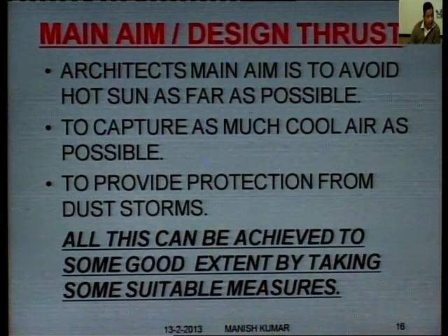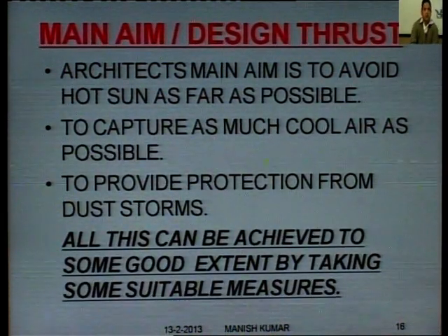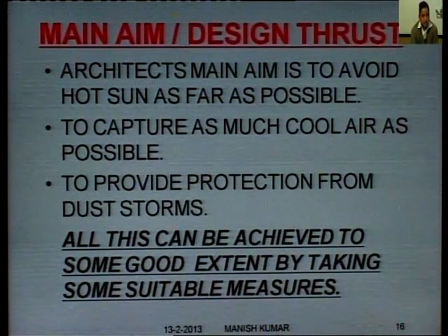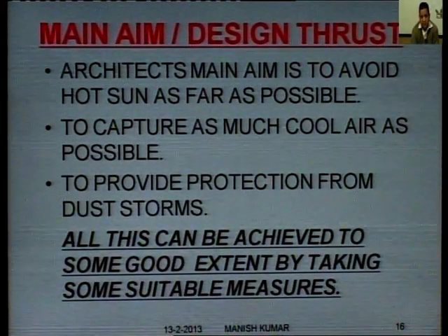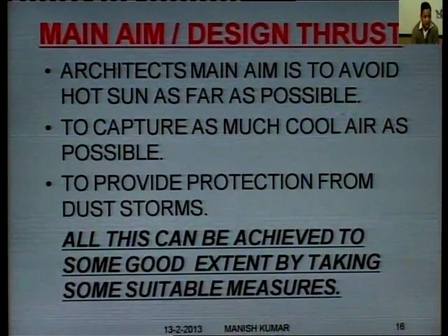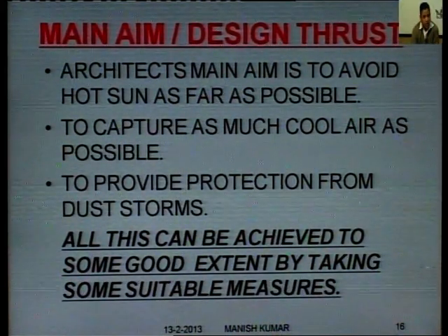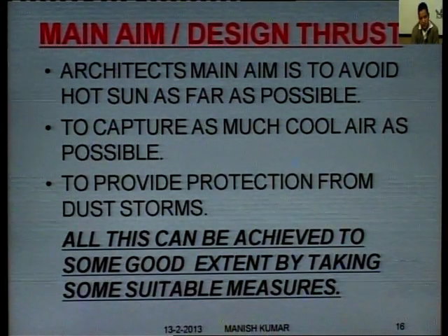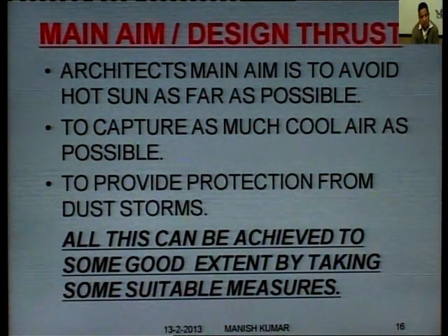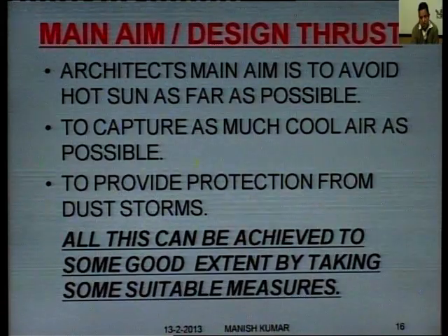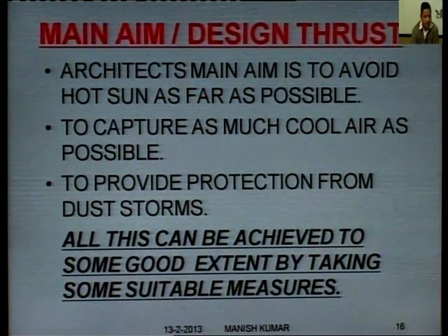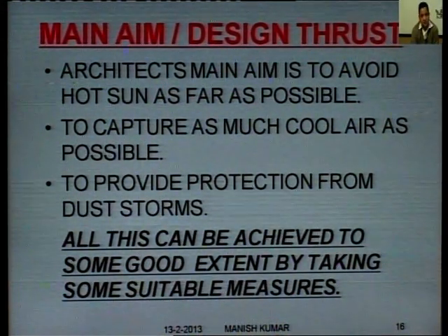Now, what should be our main aim while we design in this type of climate? First, the architect's main aim is to avoid hot sun as far as possible. Second, to capture as much cool air as possible. Third, to provide protection from dusty storms. So these are the main thrust areas which architects or builders should concentrate on.